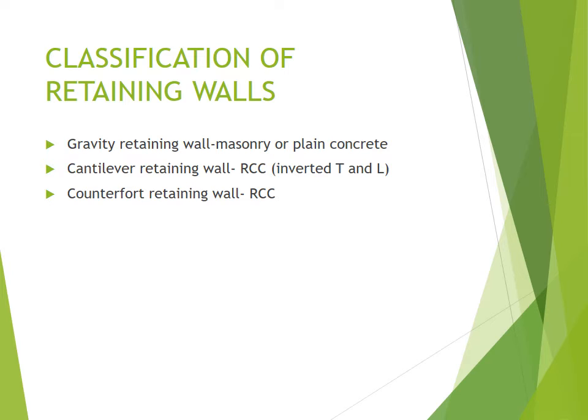They enable base and stem to act as slabs spanning horizontally over or under the counterfort. The counterforts are normally designed as T-beams of tapering sections. So they are spaced at distances of 1/3 to 1/8 of the wall height. The base of the counterfort should be well tied into the base slab. So these beams, they normally have the wall designed to act as a series of beams to resist soil pressure.